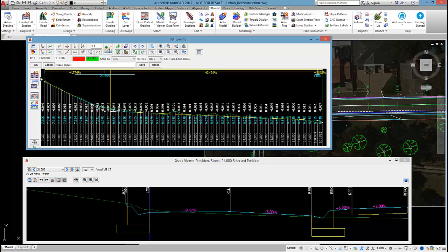Now it can be hard to set up a suitable design for the string just in this particular vertical profile view. What you can do in civil site design is create what we call design constraints, which are basically envelopes that project out from another code or string.